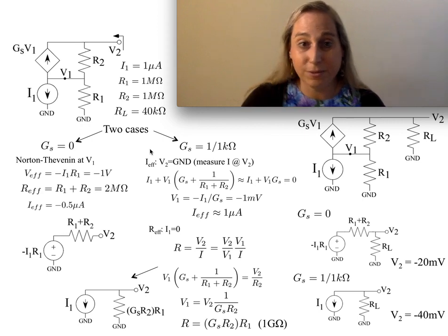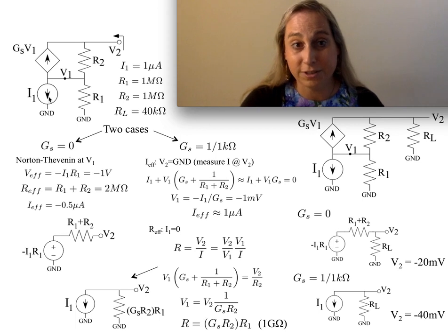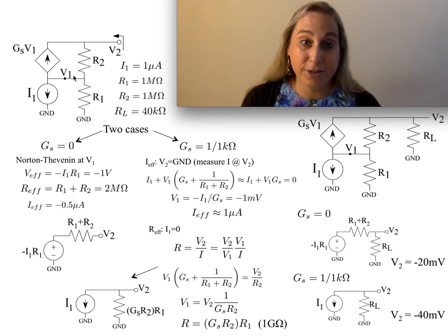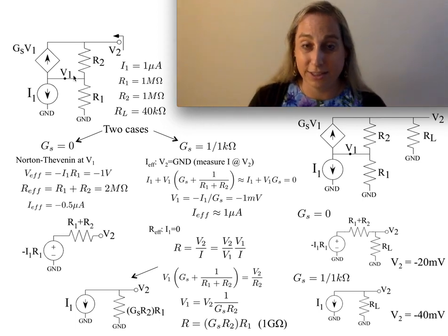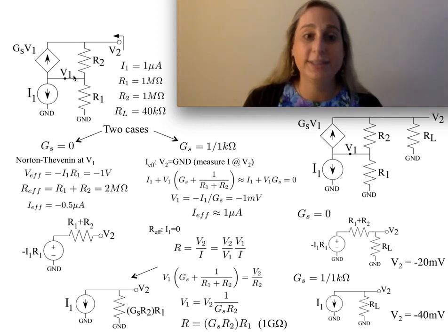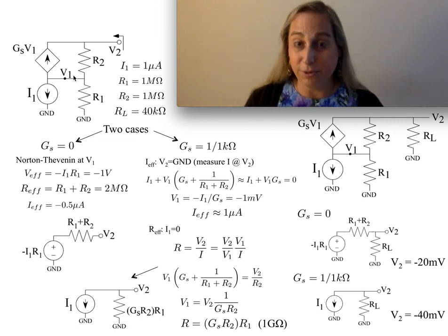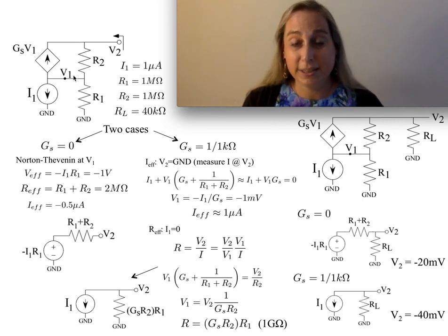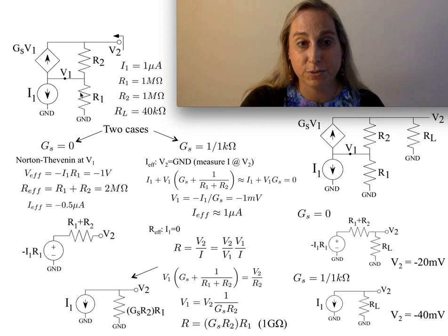Now, for those of you who are looking at this from a transistor circuit perspective, think in this case, this could be a current source. This could have been a transistor acting like a current source. This upper structure would be what's typically thought of as a cascode configuration. And in that situation, we know it does a couple things, at least qualitatively. One is that it will simply just have the current go through. Number two is that it typically makes this resistance here look a whole lot larger.